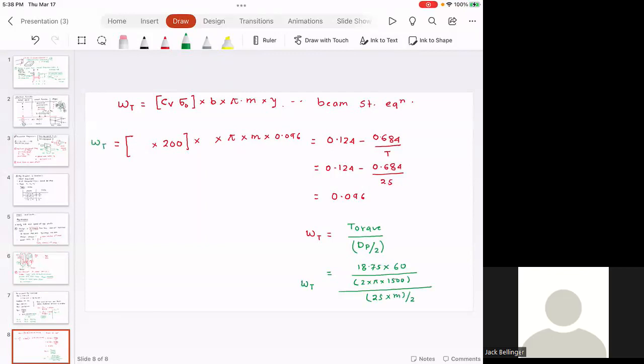Why did you put that 60? Okay, because power and actually I need to multiply by 1000. I actually took a shortcut. P is equal to 2 pi n T divided by 60 because it's given in RPM, and power is in kilowatts. So to convert that into watts, I had to multiply by 10 to the power 3. I just took a shortcut. The point here is, understand, you have an M floating around on the left hand side and you have an M that is floating around on the right hand side. Do you agree with me?